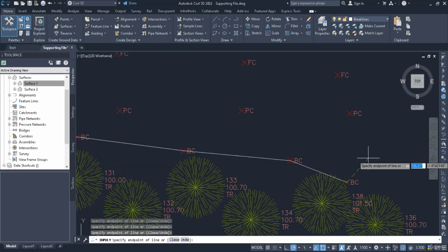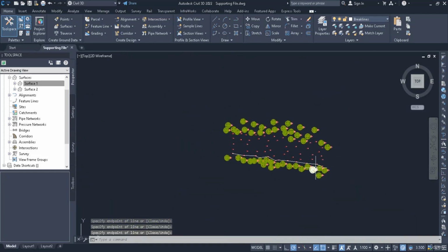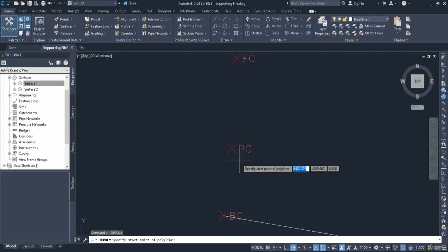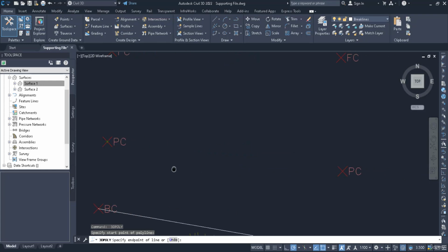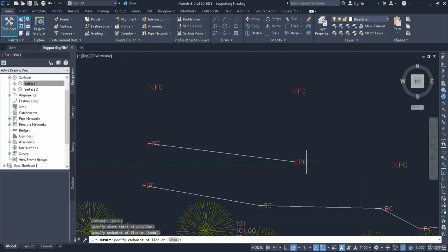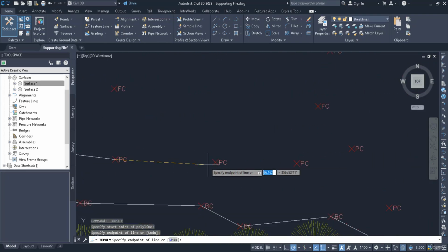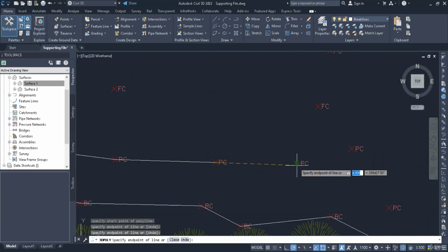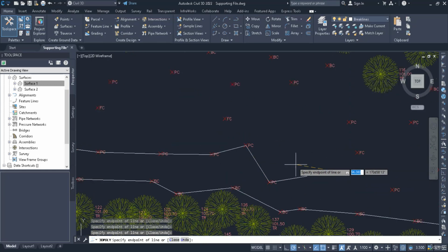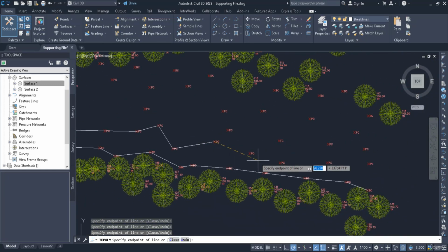Well, I would like you to experiment it yourself as well. If you go for the standard polyline, it will create the line in 2 dimensions. The elevation of that line would be 0. However, if you go for the 3D poly command, it will create the polyline with different elevations. This is a very basic key and you must remember it.